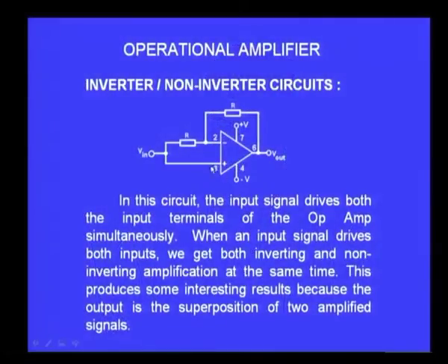You might remember we discussed the superposition theorem. I am sure many of you would immediately recognize that using the superposition theorem we can understand the working of this circuit. So, what do we have to do? It is very simple. If you see on the screen, I now assume the V in is driving both the inverting as well as the non-inverting input. So, if I now ground this non-inverting input